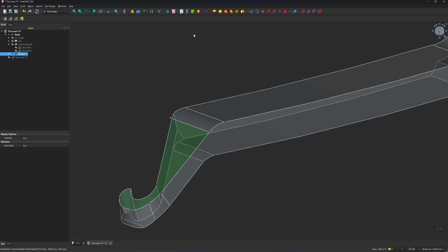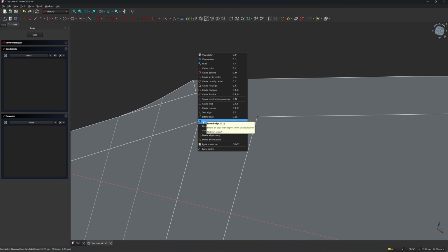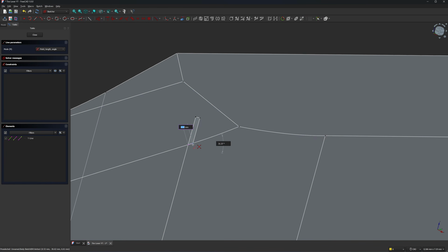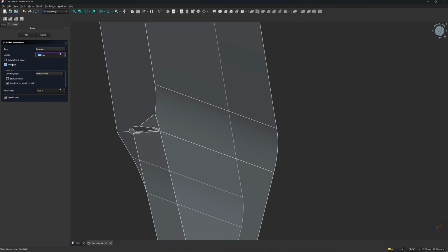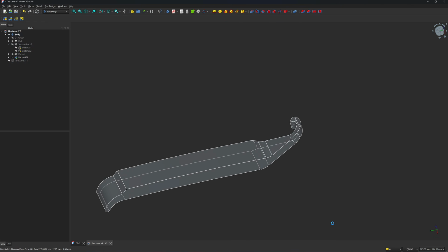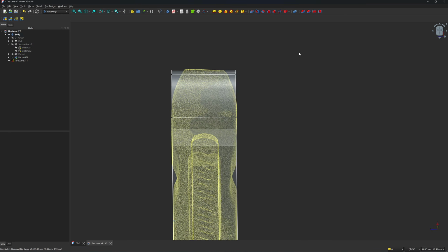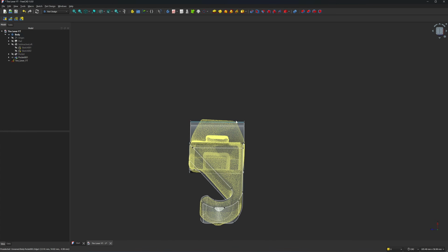Okay, let me click on this, click on sketch, create external geometry. Okay, I'm going to cut this one out, create a closed profile, close, use a pocket command, reverse, okay. So now we have a clean solid. Let's save it. I will make one more cut here on this lever. I think it's rotated. You see the top of the lever is not level.